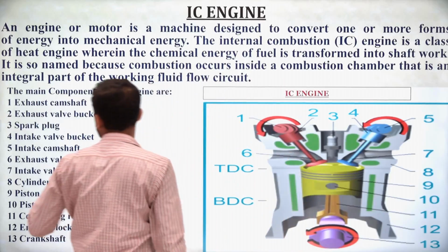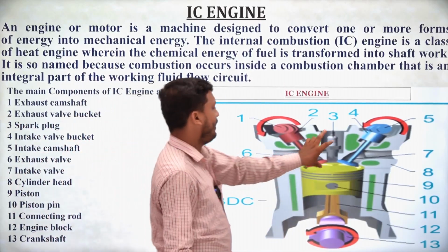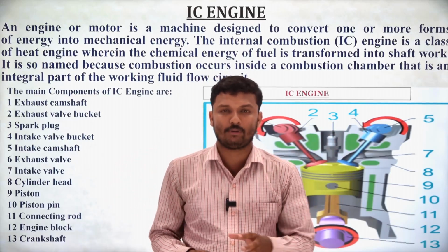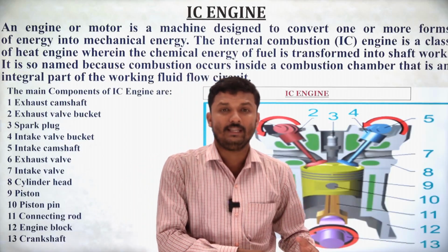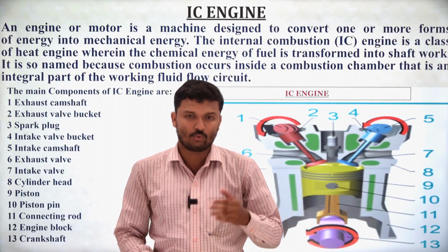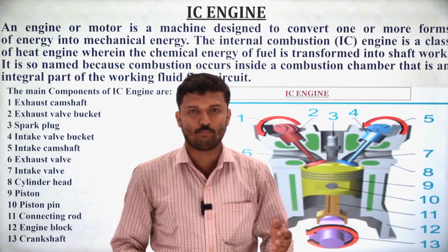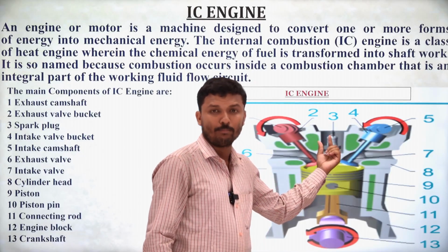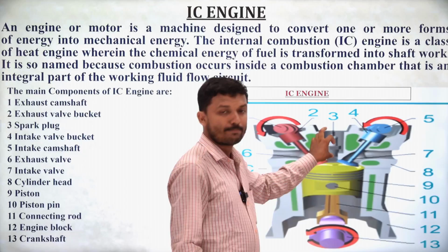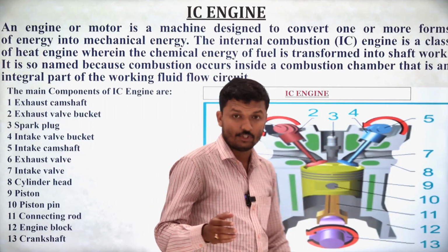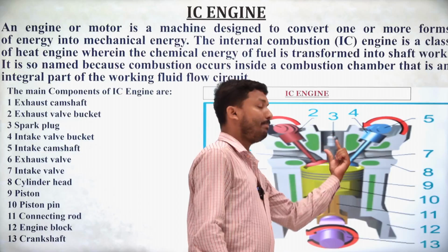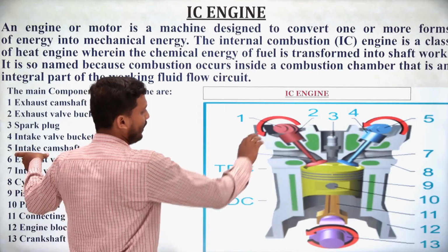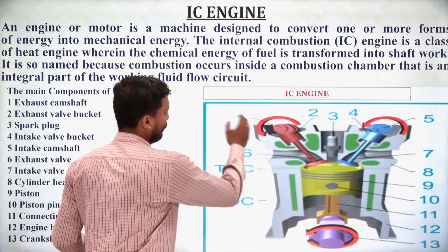Next, number 3, the spark plug. In the spark plug, the spark is generated. I already discussed the spark plug details in the previous classes on the ignition coil and ignition chamber. Go to that video to learn more about it. The spark is generated over here, and this helps to burn the fuel. In the diesel engine, generally this spark plug is replaced by a fuel injector. Next, numbers 4 and 5 I already discussed, same as 1 and 2.